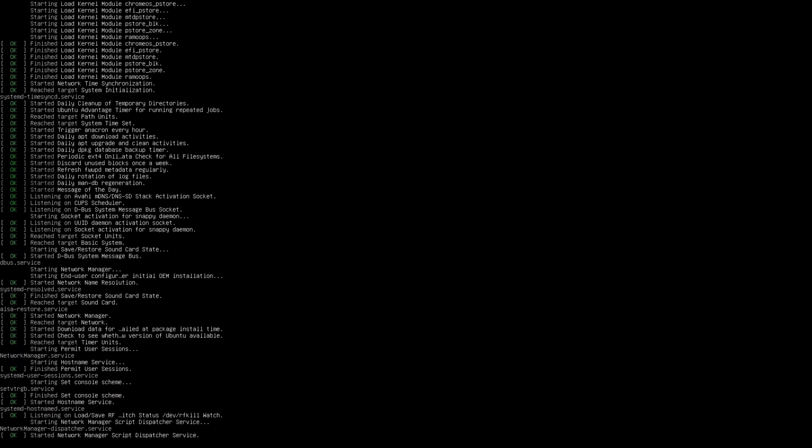After you have downloaded the image, you need to decompress the image and then flash it to a microSD card. We recommend using a bit-for-bit imaging utility such as Win32 Disk Imager for Windows, Apple Disk Utility for macOS, or GNOME Disks for Linux to write the raw image to the microSD card. Please avoid using Etcher and other tools that perform skips, as they can cause the image to not boot.